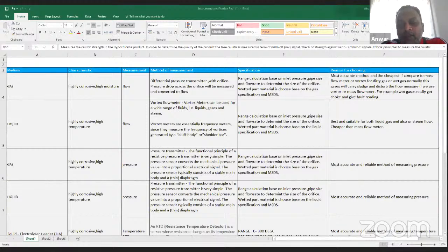Secondly, how fast you need to transfer. When you ask how fast you need to transfer, that will determine the downstream condition and also the upstream condition, because you do not want to oversize this pump unnecessarily.